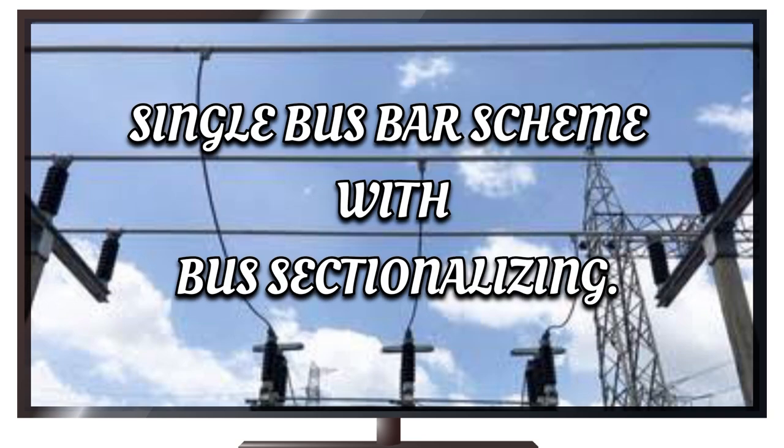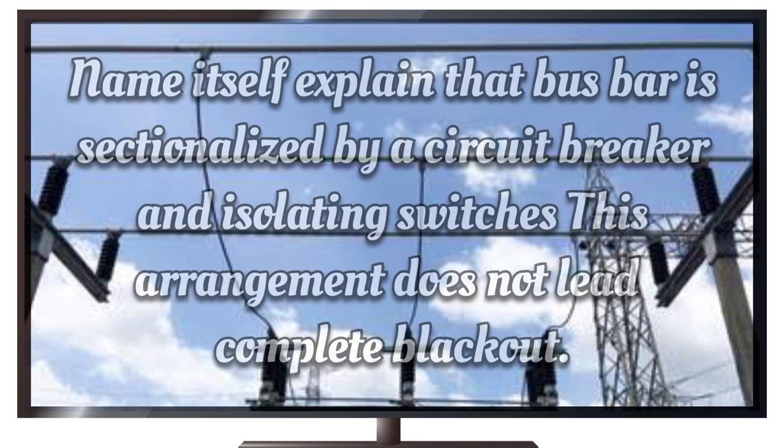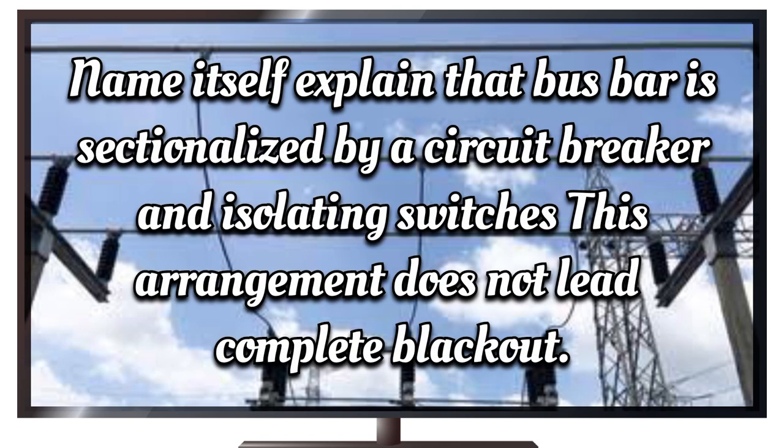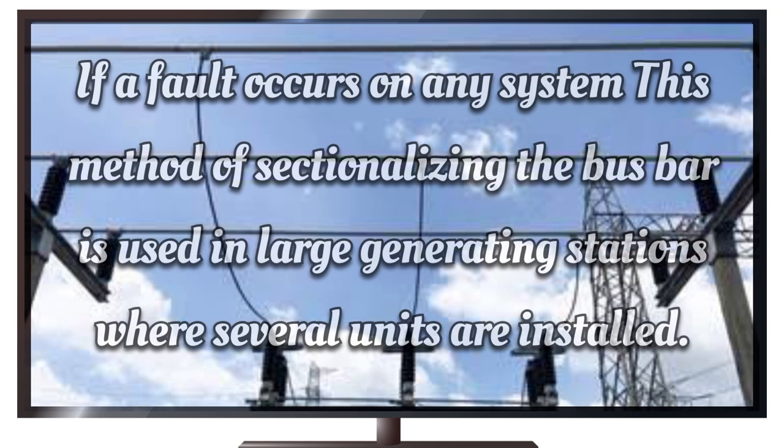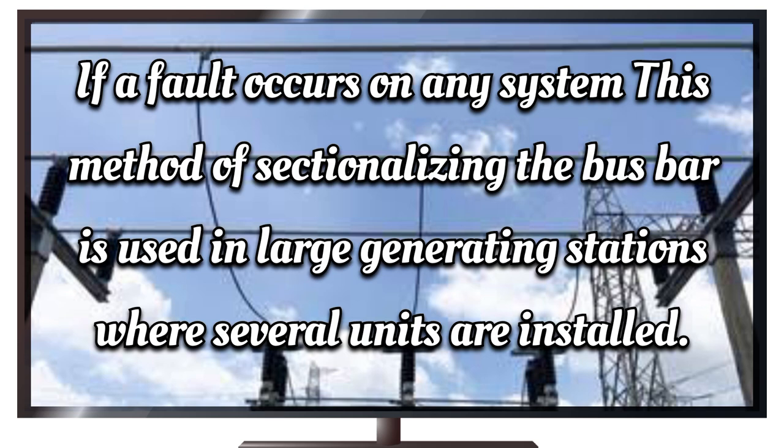Single bus bar scheme with bus sectionalizing. Name itself explains that bus bar is sectionalized by a circuit breaker and isolating switches. This arrangement does not lead to complete blackout if a fault occurs on any system. This method of sectionalizing the bus bar is used in large generating stations where several units are installed.